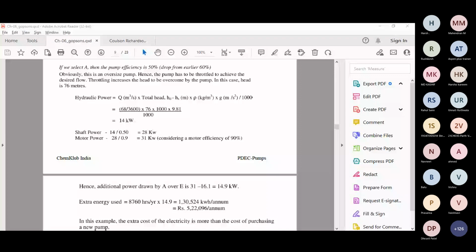my bypass valve will open and my inlet valve will close. So in that case my flow rate will be there and the pump will always be operating. All my flow rate will go through the bypass of the heat exchanger and come back to the tank. In that way I can do it. The bypass line is again acting as a recirculation line only. So that is one of the options.